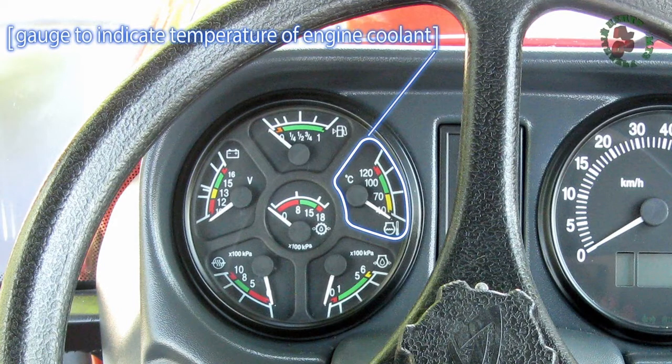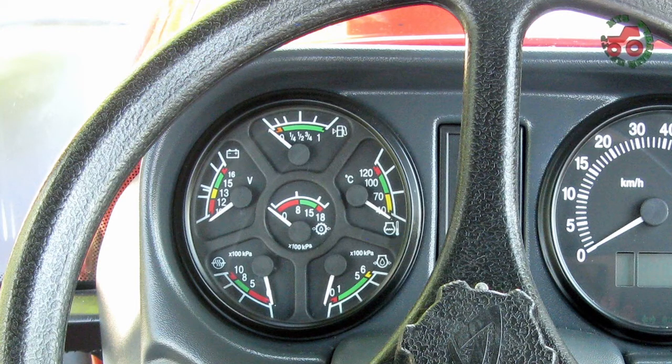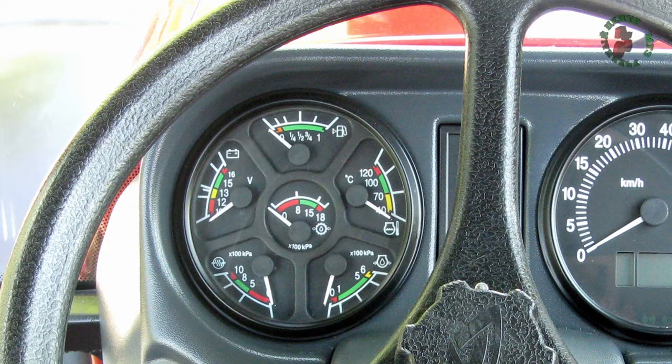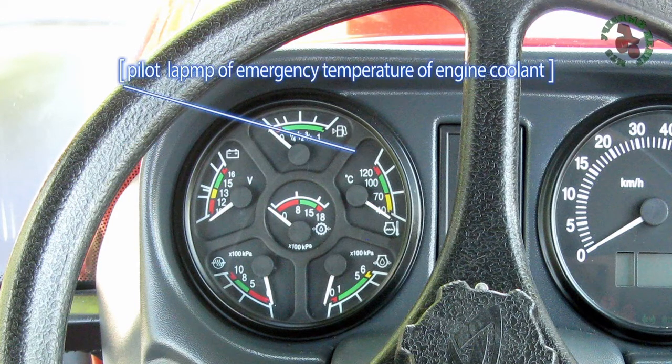Gauge to indicate temperature of engine coolant. The scale of this gauge has 3 zones: information zone, working zone, emergency zone. Pilot lamp of emergency temperature of engine coolant operates in 2 modes: flashing at coolant temperature from 109 to 112 Celsius degrees, glows constantly at coolant temperature from 113 degrees and higher.